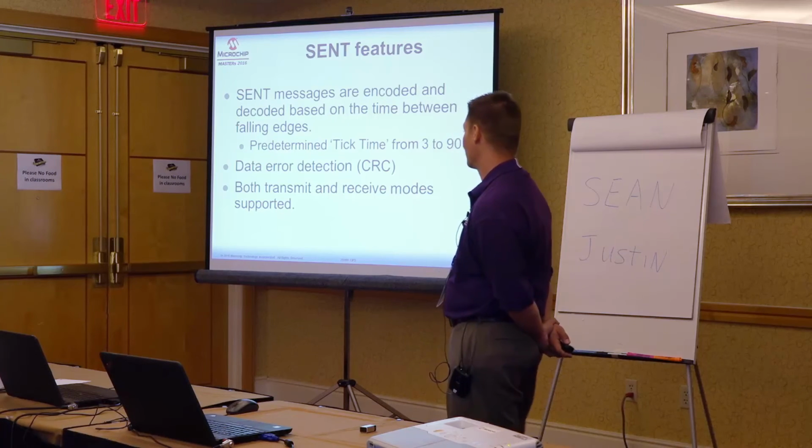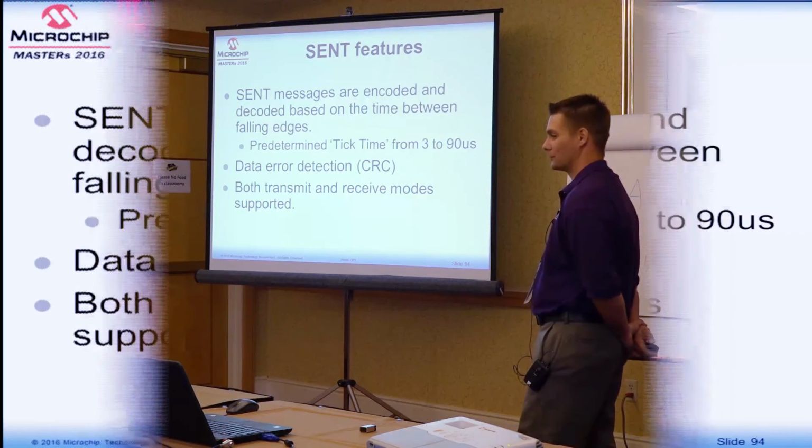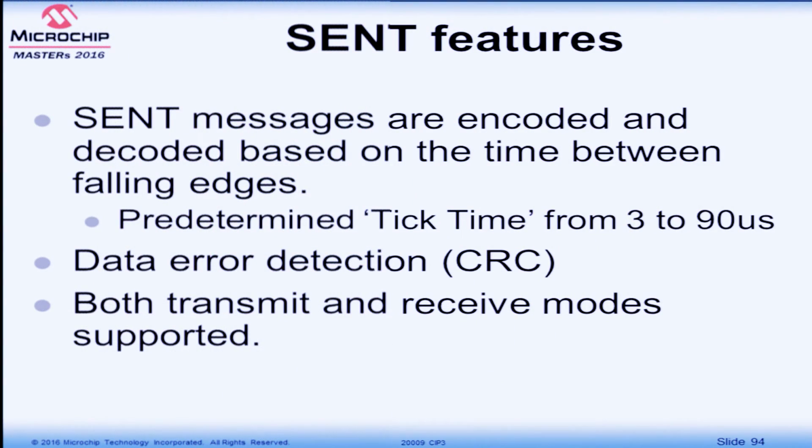So how does it work? Well, the messages are encoded in the time between falling edges. And the system is based on what they call a tick time. And that is a predetermined time period that both the transmitter and a receiver are already aware of, so they know what synchronization pulse it should be looking for.